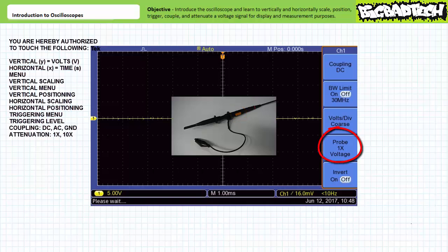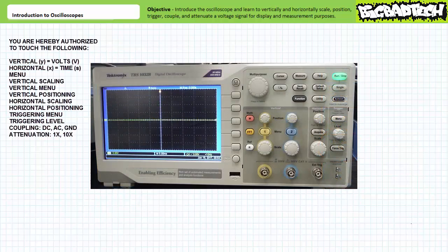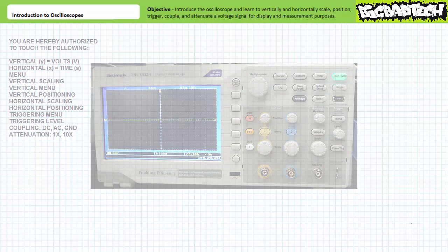A modern oscilloscope can compensate for probe attenuated input using the channel menu to rescale the signal. As brief as this list seems to be, I will be so bold to say that every broken oscilloscope I've seen, by the way, I'm using quotation marks with my fingers, isn't broken, but rather one or more of these basic aspects aren't being taken into account. Let's examine each aspect in turn.